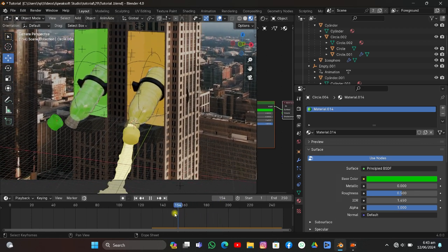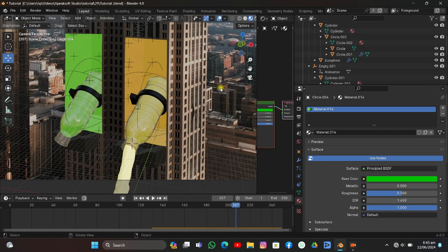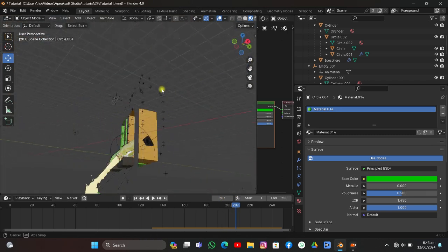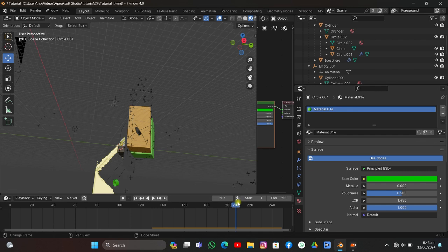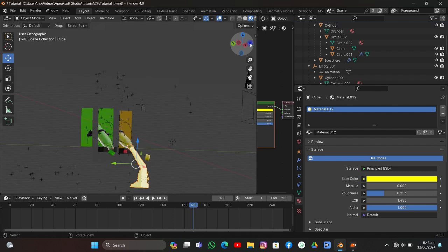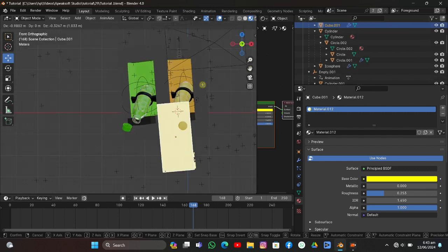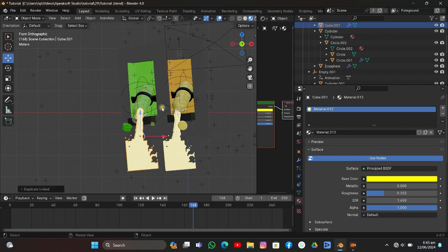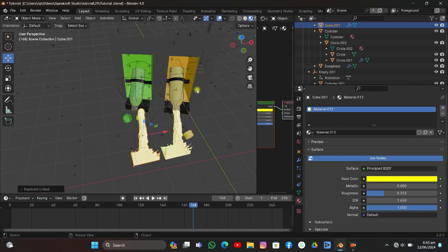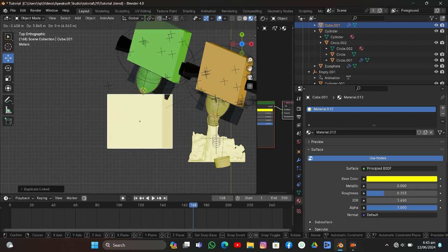We can just duplicate the existing fluid to the other object, change its material, and that's it. It is fairly simple. And if we just look at this, okay, that is totally fine. Select this object, go to y-axis, hit Shift D, duplicate it. On x-axis, you can also hit Alt D, so it will instance this object into the other side, but it might cause you problems later on because you will have the same property for both of the objects.